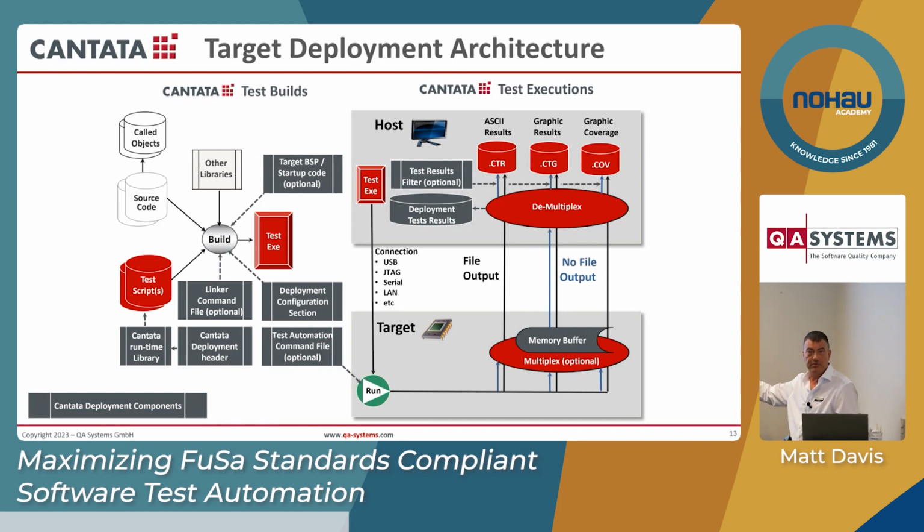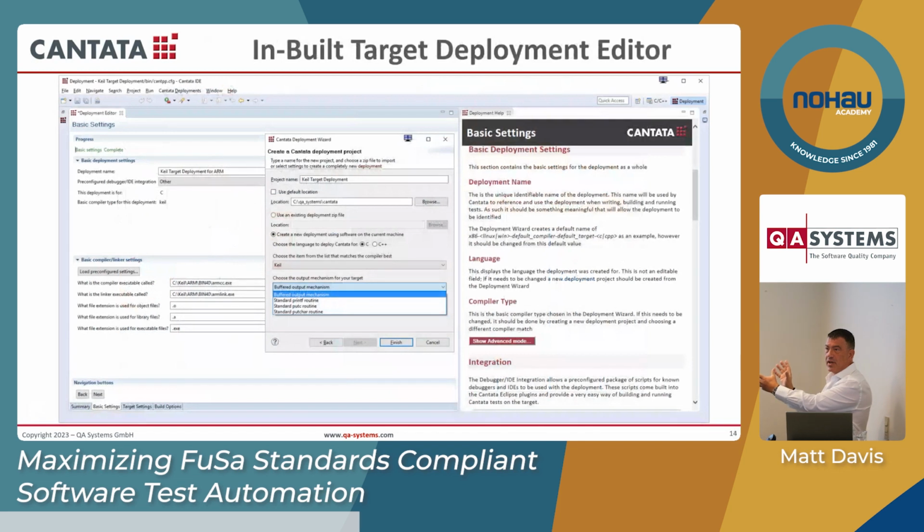In most cases, people don't. They're not running on a full fat RTOS. They're running on a bareboard or a microkernel or whatever, in which case we use lots of different mechanisms to take the data back from the target to the host. Memory buffers can be flushed. We can use different types of connections, basically the way you would work if you are getting any analytics back from your target. And when I mean target, I don't just mean a physical board. It could be a physical board, it could be a simulator, in which case the comms is much easier, or an emulator, etc. Anything that cross-compiles. And inbuilt into Cantata is a full deployment editor to allow you to configure and set up those configurations for a target.